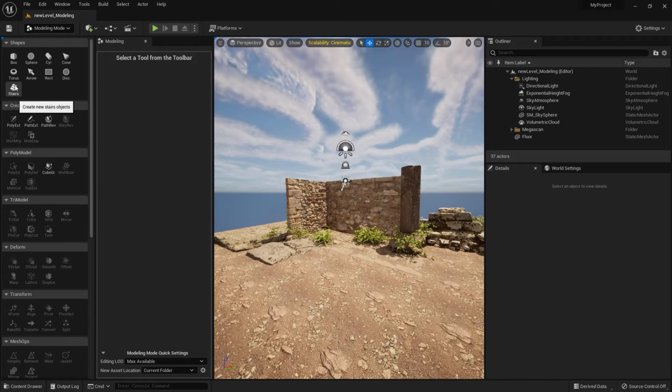So with that out of the way, now we know how to load the plugin. Let's go over one more tip that you need to be mindful of at any point during the modeling process. If you feel like the scene starts slowing down, there are a few things that you can do to alleviate the pressure from your system. The main culprit every time you use a modeling tool and your scene starts slowing down is the use of signed distance field, or SDF.